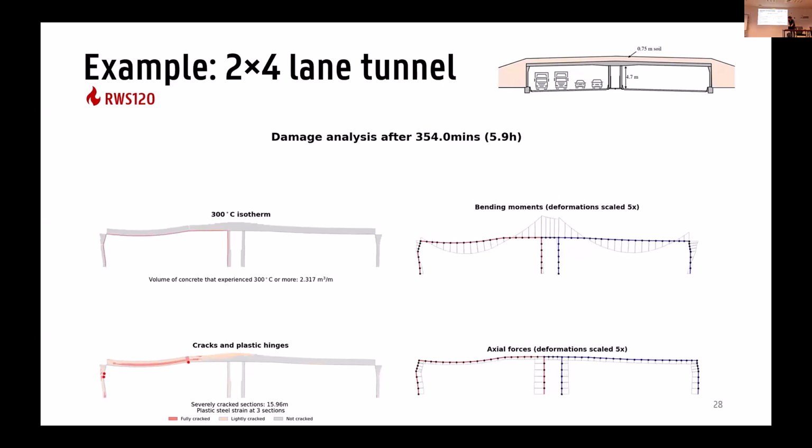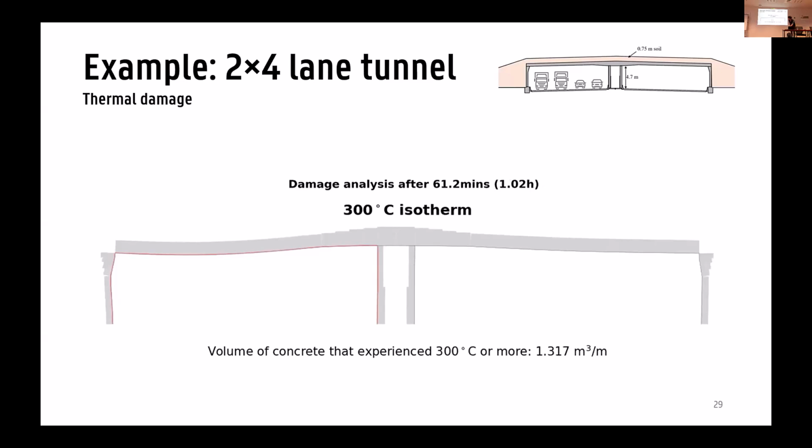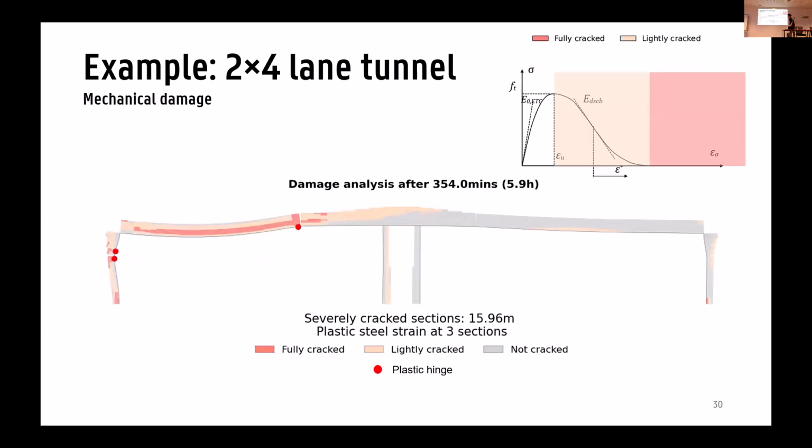I'll zoom in on the graph on the upper left first, just to show you that you can quantify how much volume of concrete is being heated more than 300 degrees throughout the fire, and which can also tell us something about the cost of the repair works that are needed if we can repair it. But then more interestingly, if you look at the mechanical damage, we get the following plot.